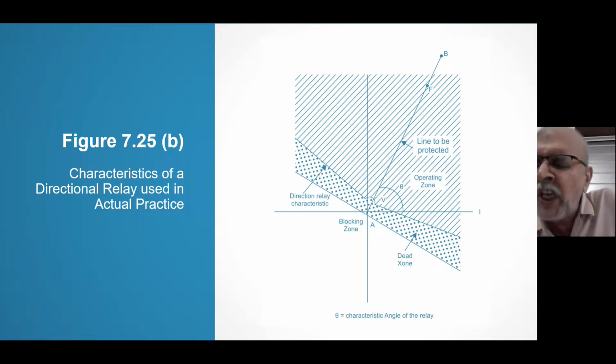Dead zone is only and only in case of triple line to ground, when the earthing switch is on and I am inadvertently making the breaker on. These possibilities are also very less because there is an interlock. But if the interlock fails, the possibility is hardly 0.2%.